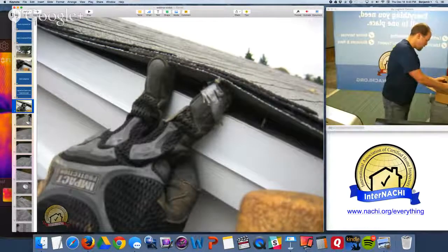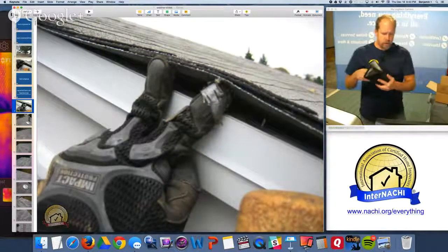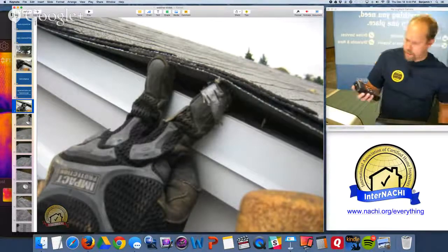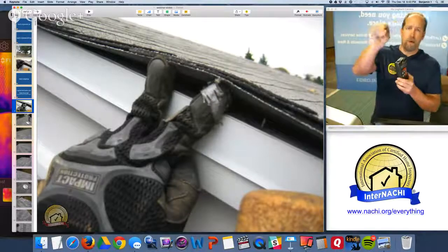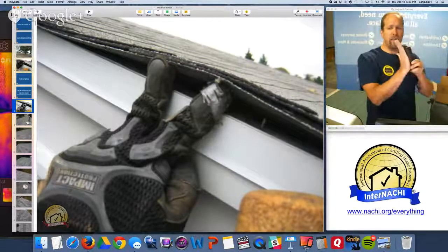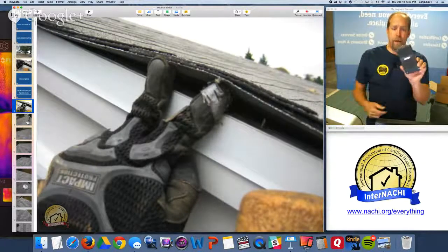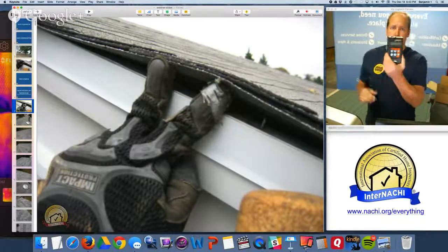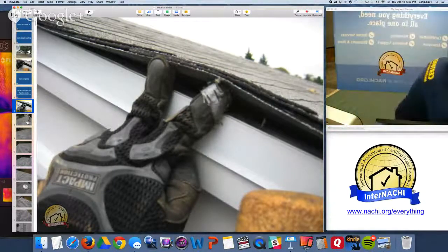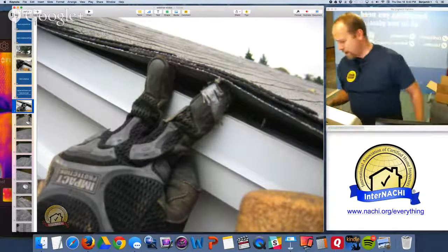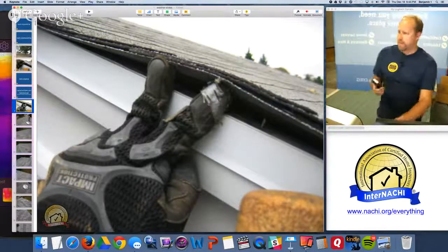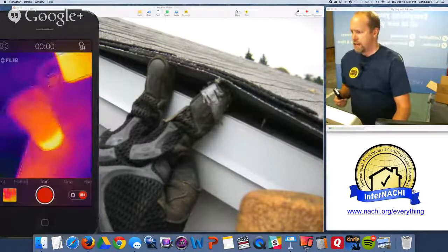Here's another tool that I use. It's not required by the standards of practice, but it's a moisture meter. You can stick in your probes or use non-invasive, and it beeps and gives an actual quantitative value for the moisture that you're looking for. And when I do an infrared scan, because I'm infrared certified, and that's a certification that InterNACHI provides,